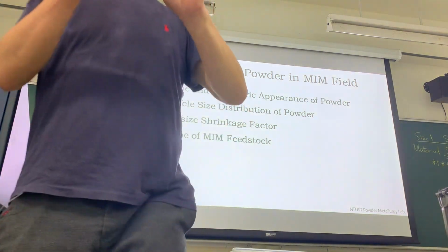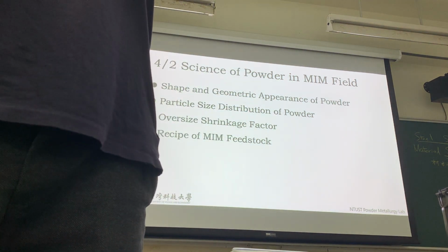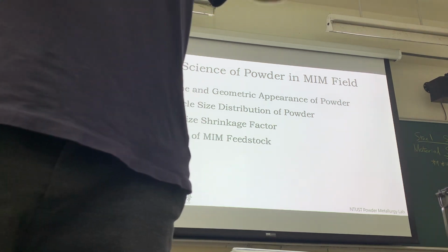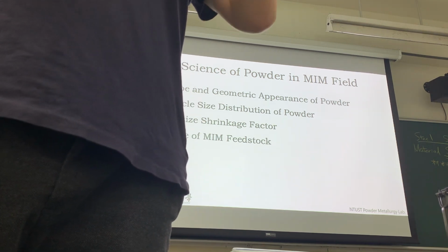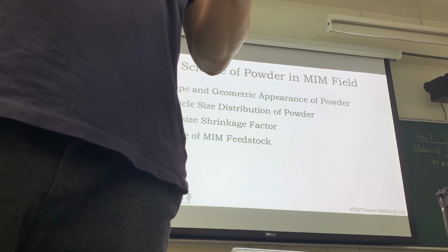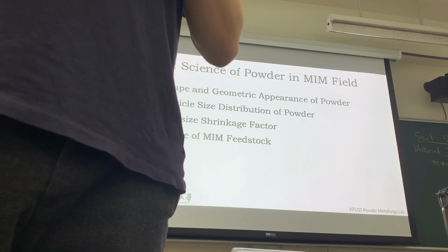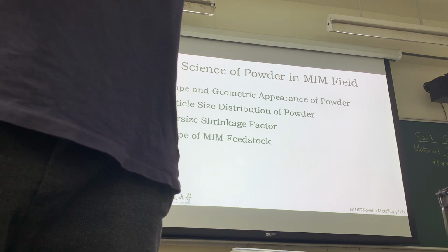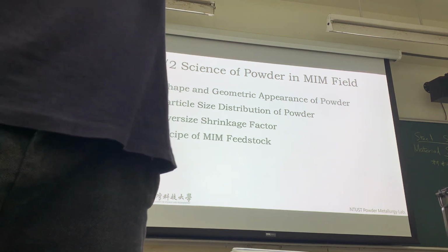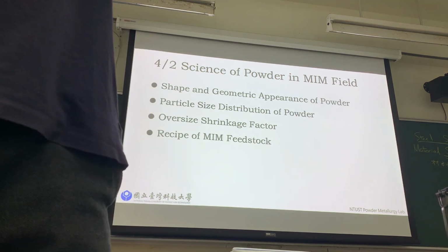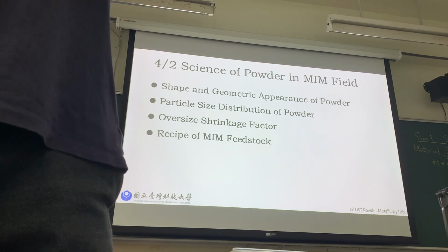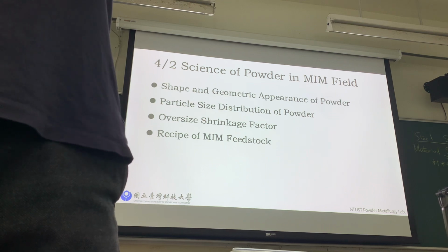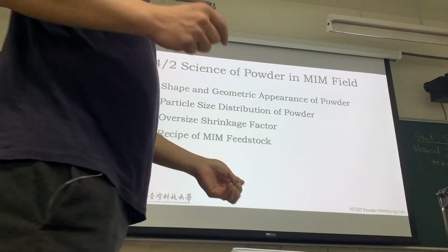The mold should be made a little bit bigger. Then after we get this green part, we can do the post process, for example machining, grinding, polishing or something. This one's dimension should become smaller and approach your drawing spec. You're just thinking about our drawing defining the spec, then your parts should be close to your drawing. That's very important.